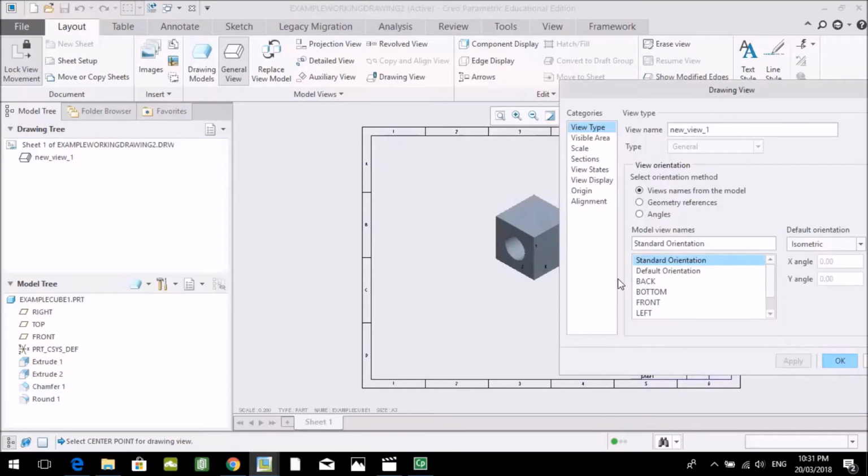An isometric won't need dimensions according to AS 1100, so we're just simply creating a scale for this drawing and generating on the page. Often when I'm doing my working drawings for different products that I design, I will simply start off with an introductory drawing that shows what the model is going to look like before going into my detailed drawings that are showing the third angle projection and more detailed views of specific parts, etc.